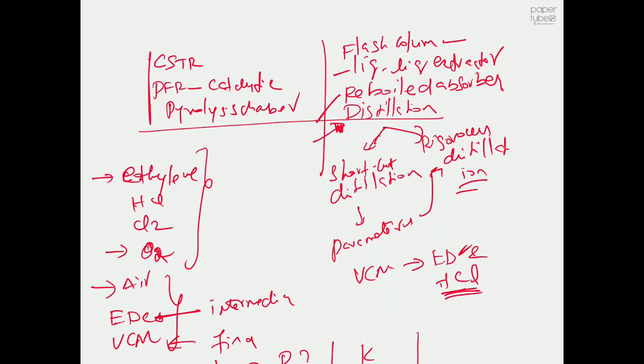For example, imagine if you have a fluid. In fact, your vinyl chloride monomer itself will condense at a negative temperature, somewhere around minus 27 degrees centigrade. Yeah? So in that case, I'm not sure, we will check that when you are going to design the distillation column. In that case we cannot use water from the river. We have to think about using some other refrigerant. So we will learn all those things in the final part of this lecture, when you are going to deal with the distillation column.